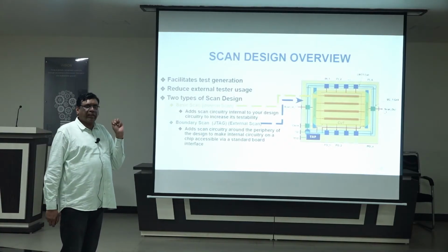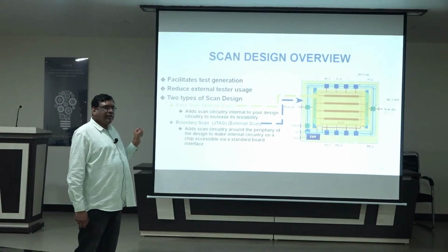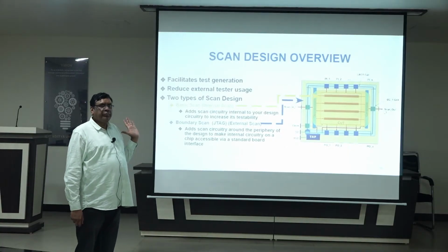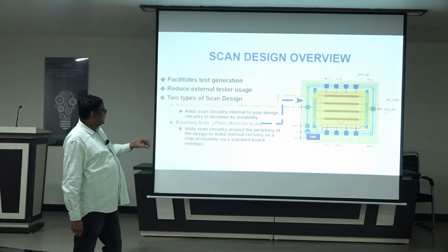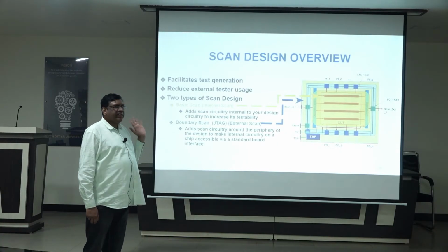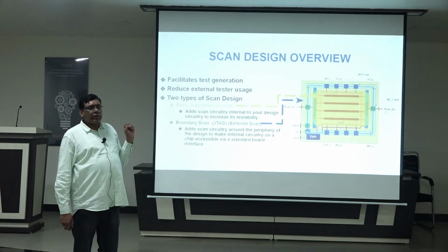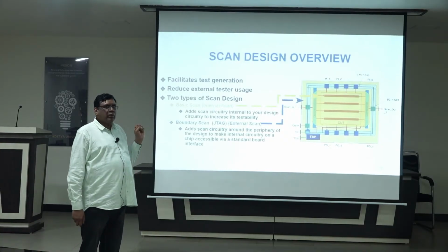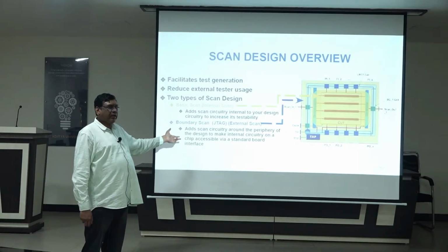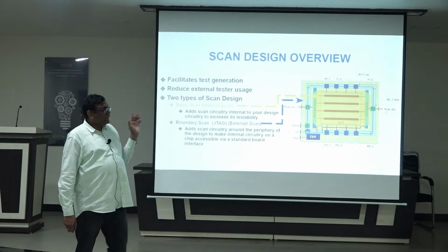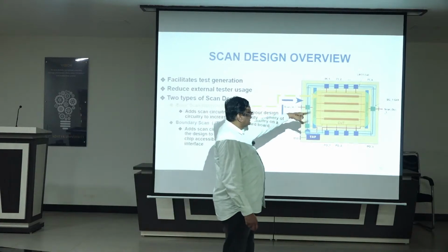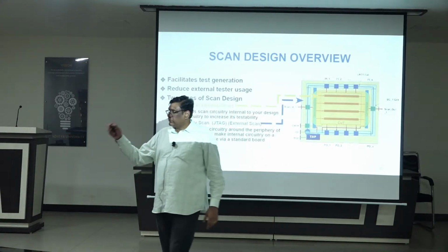There are two types of scan: one is the boundary scan, another is the basic scan. Basic scan we generally call internal scan, and boundary scan we call external scan. But the more popular is the internal scan. Boundary scan is very little, but most of the effort has to be done on the internal scan, which verifies all the logic internally.